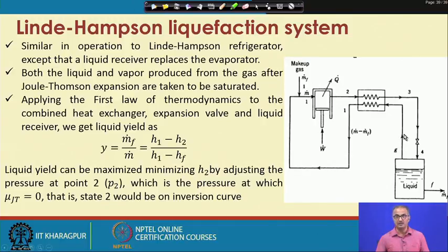It is the same as the Linde-Hampson refrigeration. This vapor is taken and is now heated up by the incoming gas, and the temperature ideally attained is the same as the inlet temperature to the compressor. The work requirement and the heat to be rejected remain the same as far as the total mass is concerned. The only thing is that we have another parameter, the liquid yield, which comes into the picture whenever we talk of liquefaction systems.